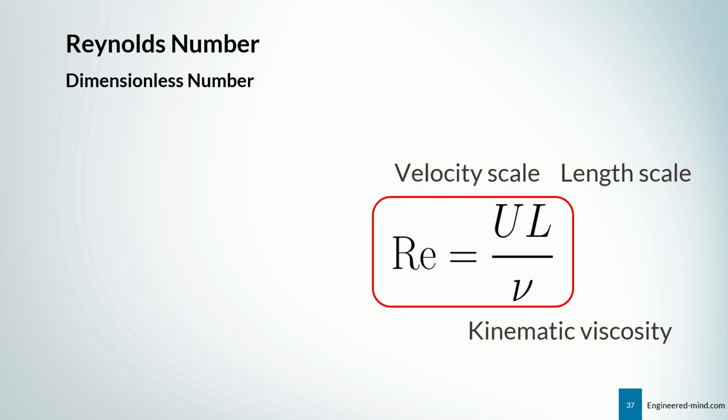What we can use, and what's often used, is the so-called Reynolds number, which is a dimensionless number, and it gives us a relation between inertial forces and viscous forces, where we have the inertial forces in the numerator and the viscosity in the denominator. So we have U times L divided by nu. And we say flow is laminar if the Reynolds number is low. And then the question also is, what is low? So you really have to have some experience in this subject, also to know in order to determine if the flow is really turbulent or is it still laminar.